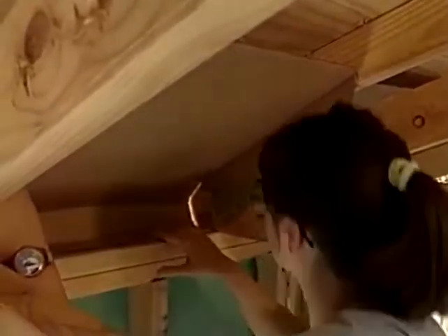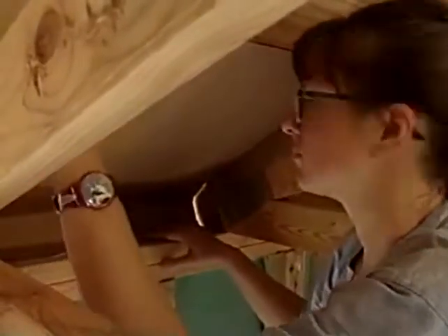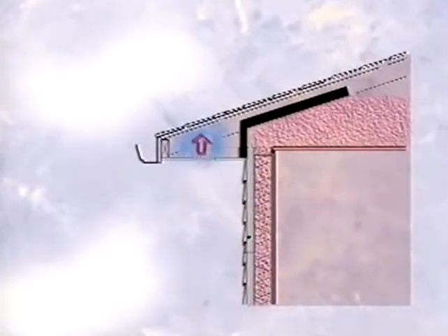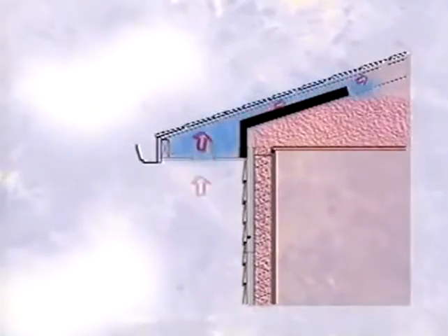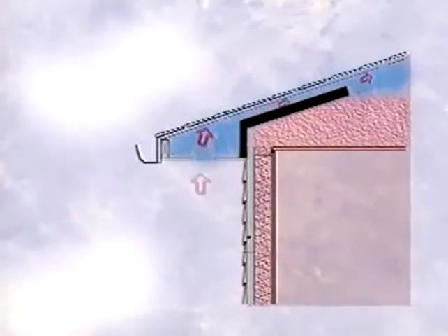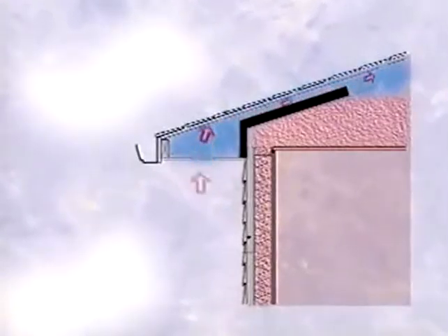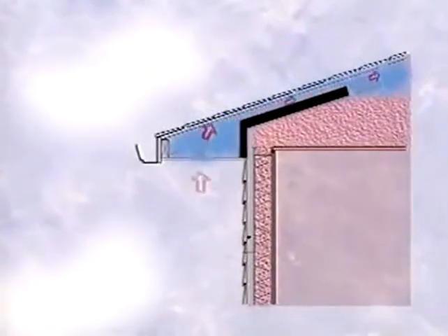Fixing this problem is easy and inexpensive. Cardboard wind baffles are available at most supply houses. They should be installed prior to insulation. The baffles block the air from entering the insulation through its exposed end, but still allow air coming through the soffit vent to circulate along the ridge. This provides needed attic ventilation, but protects the insulation from wind washing.